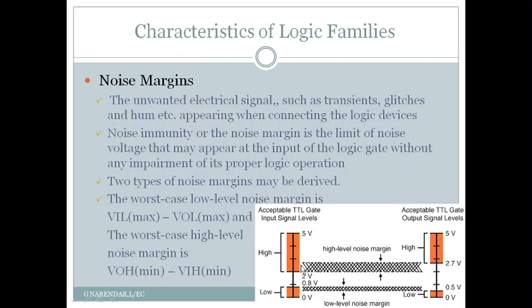After reducing the voltage below 2 volts, this voltage will not be treated as a high signal because it is out of the voltage range. So the circuit will malfunction, because it is not treating the voltage as a high signal, and this is due to the added noise.